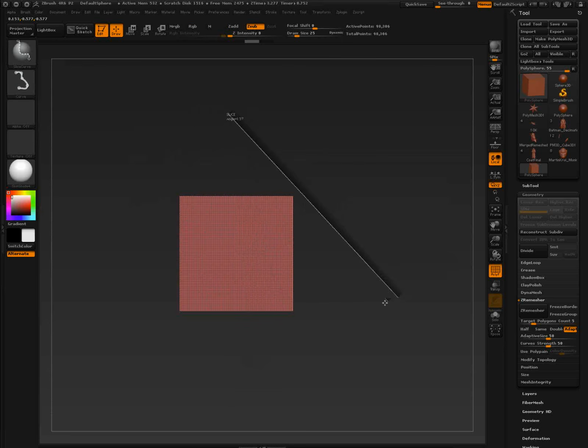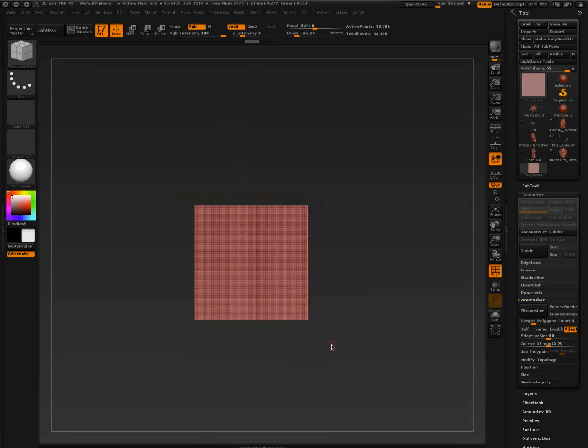That makes the line come alive. So that way I can hold the space bar, hold the Shift key, and you can see it snaps to certain degrees, right? Or I can tap the Alt key or double tap the Alt key. This is very important to understand because a lot of people will still email me, Paul, how do you hold down the Control-Shift key and the Alt key and the space bar? Why don't you want to do that? Well, you don't have to.